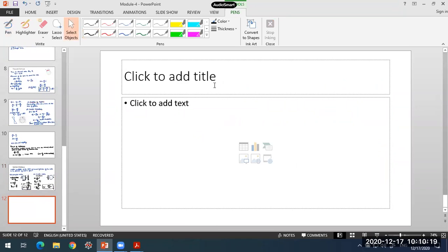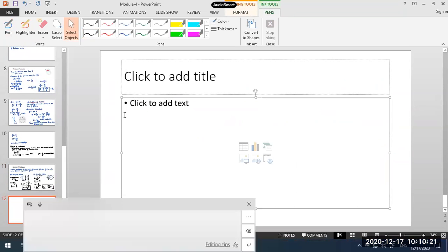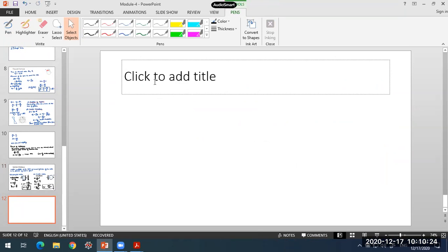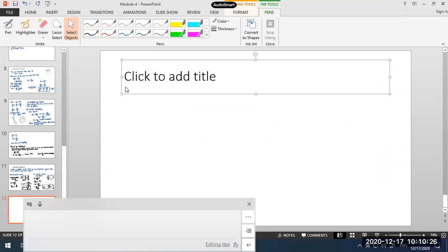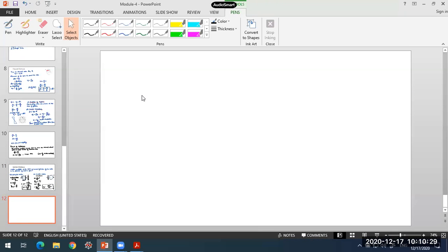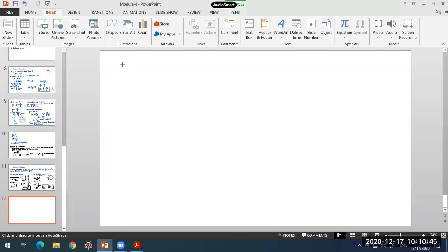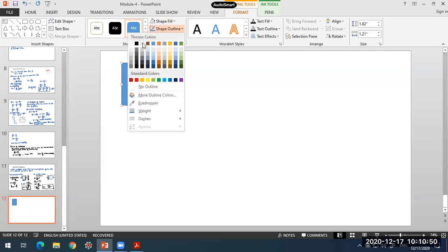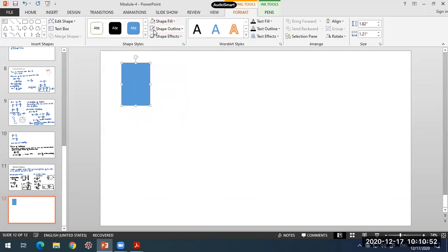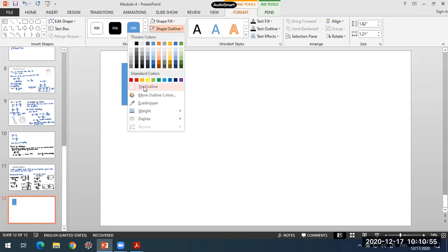If you have some T section or I section, we have to actually calculate its I value, then determine the distance of extreme fiber from the neutral axis or from the centroidal axis, and then we can do it. For that we need to do the calculation. But there are some regular shapes for which we can know or remember these values. Another such shape is a hollow rectangle section. Say you have a hollow rectangle section.